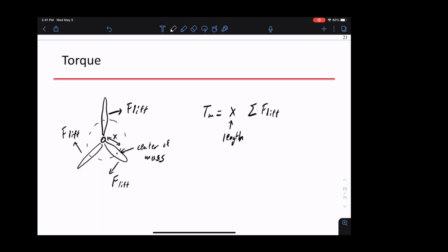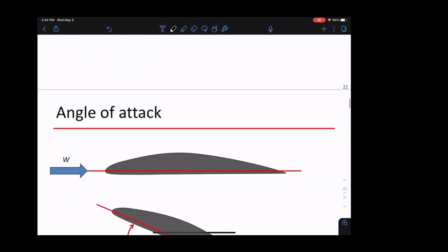So the operation of the blade is, we have wind coming in. How do I get the power I want? That translates to how do I get the correct amount of lift on the blades I want? That's our control question. So this is similar to solar, where the power is determined by the voltage as the output. Here, the power is determined by the amount of lift. So let's look at how we control lift.